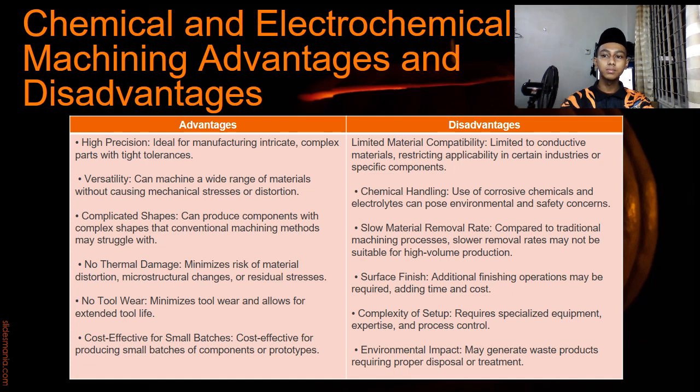For disadvantages, limited material compatibility. Limited to conductive materials, restricting applicability in certain industries or specific components. Second, chemical handling. Use of corrosive chemicals and electrolytes can pose environmental and safety concerns. Third, slow material removal rate. Compared to traditional machining processes, the slower removal rate may not be suitable for high volume production.